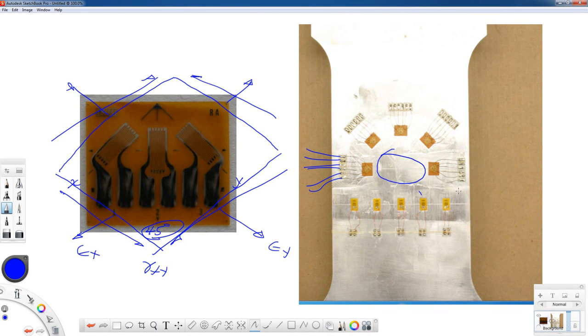Like I said, strain gauges are probably the most commonly used way to measure strain. The advantage is they're relatively cheap, maybe $5 to $10 a piece. It takes some labor and some time to put them on, which isn't necessarily inexpensive. And they are single-use items. Once you glue it on, you can't unglue it and stick it somewhere else.